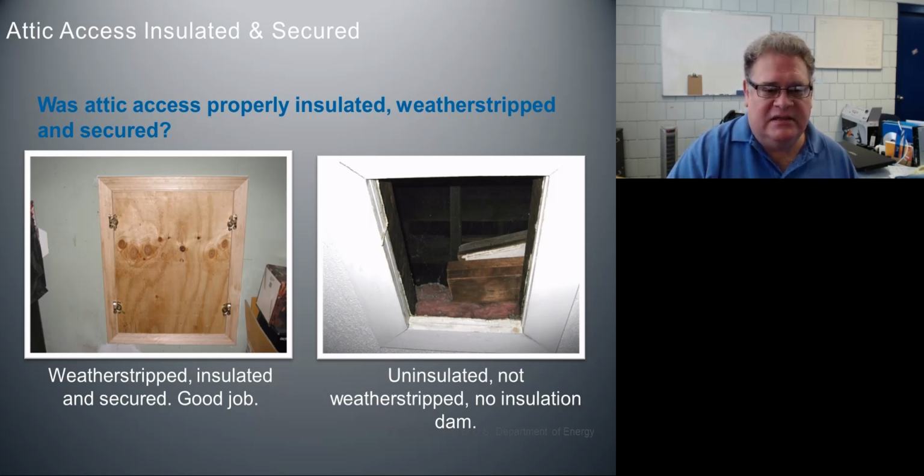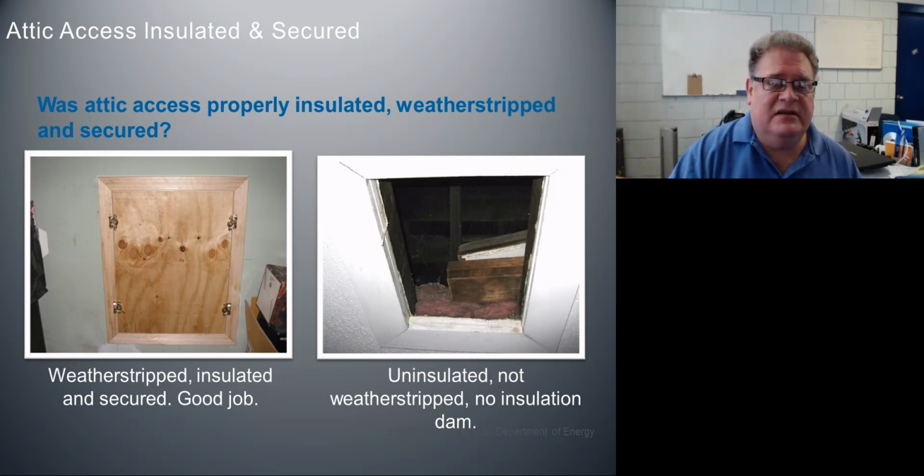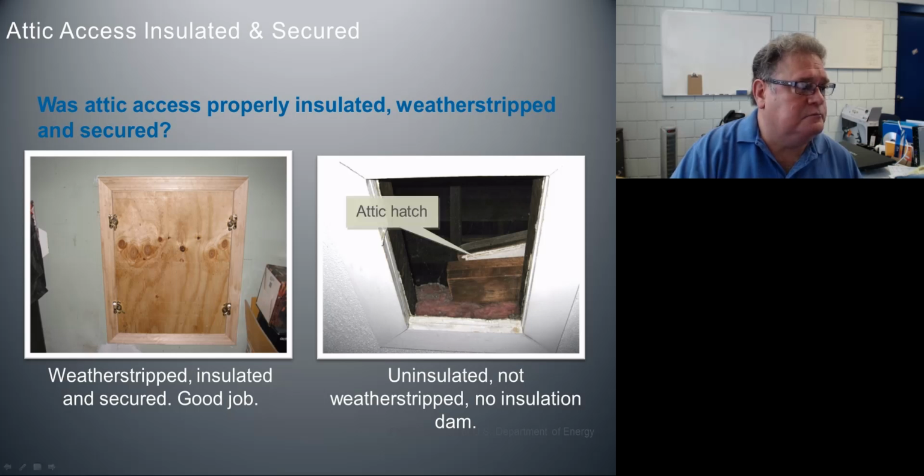The other thing is this attic hatch on the left looks new, so if it's a modification or new, it's going to have to comply with building codes, which means we've got to have the headroom above it and a minimum size. But I do like the use of the window sash locks here to put pressure on that weather stripping and to compress it, to push it down so that it does a good job. Okay.